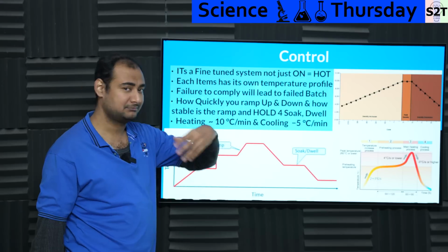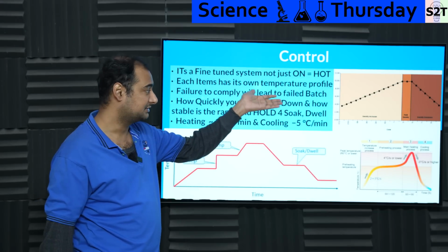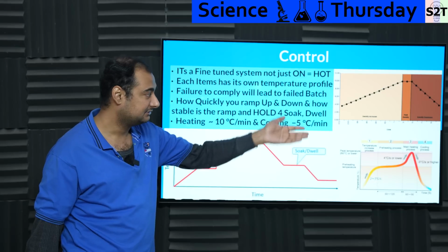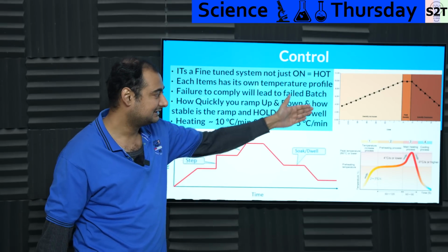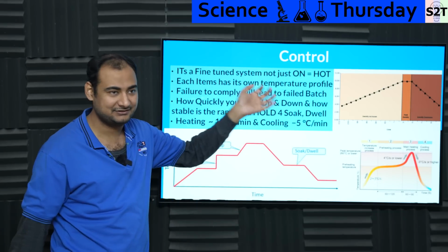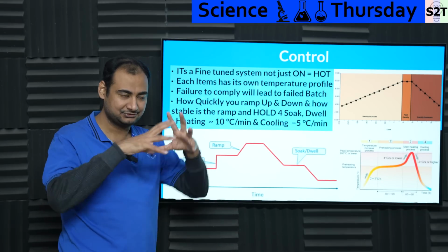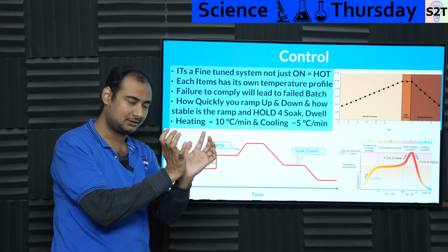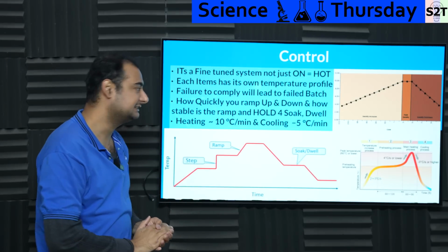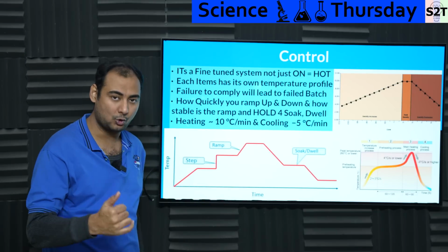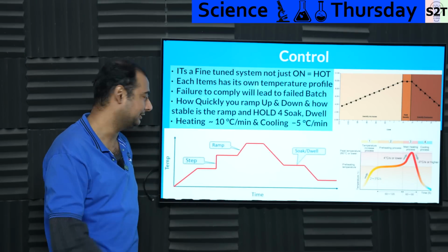And if you're dealing with ceramic pottery or insulators or things of that nature, you also have to worry about density increase, peak density, and density decrease. You would think temperature keeps going up, right? It reaches a point where it will backfire on you. Not to mention the structure might fail, like you might have a shape and it's like, bleh. So all of these things have to be considered. This graph has to be controlled: ramp up, hold, soak, dwell, then cool down, all of those things.